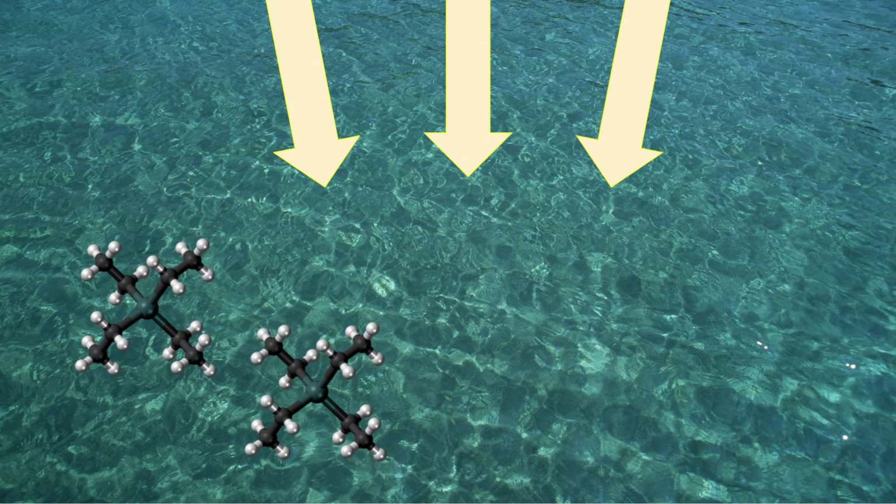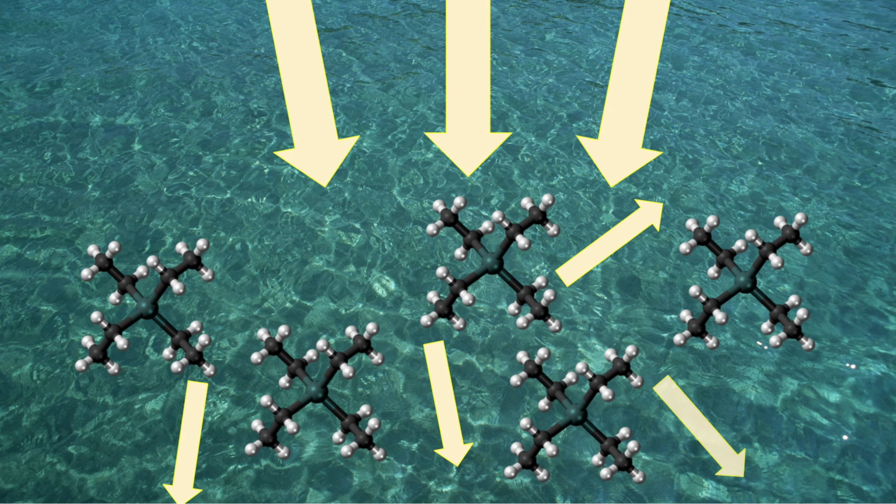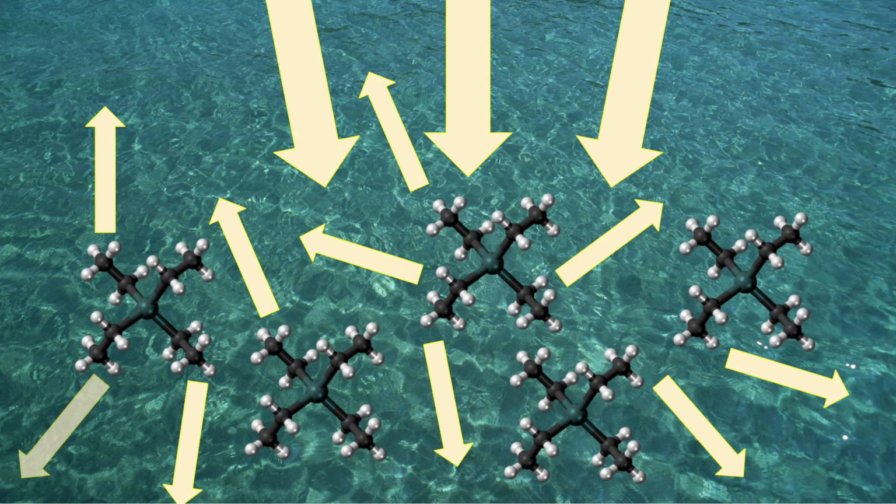Turbidity refers to how much light is scattered by particles in water. The cleaner the water, the less scattering occurs. But when corrosion or lead particles are present, they cause the light beam to scatter intensely, a principle measured by optical sensors in nephelometric turbidity units, or NTUs.